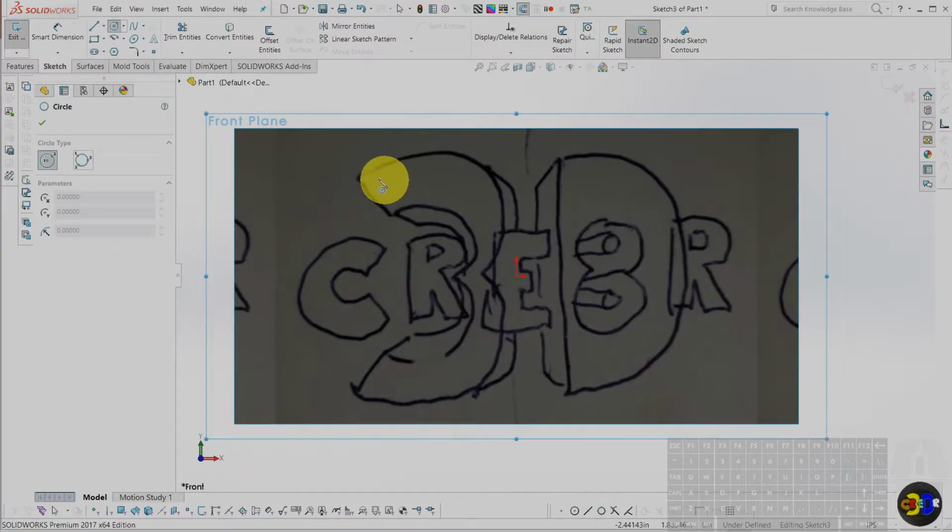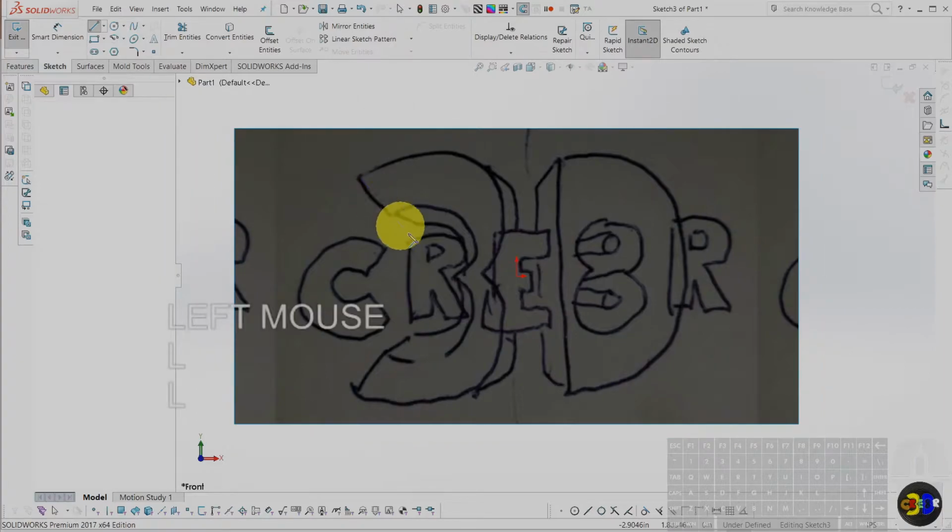And so for that I will need a plane, a sketch for the front face of this 3D, and another sketch set back a ways for the rear hidden surface, and then I will do a loft likely between them, or a series of lofts and probably Boolean operations to get to where I want, especially, well, mainly for the D/8. Alright, so I will start sketching.